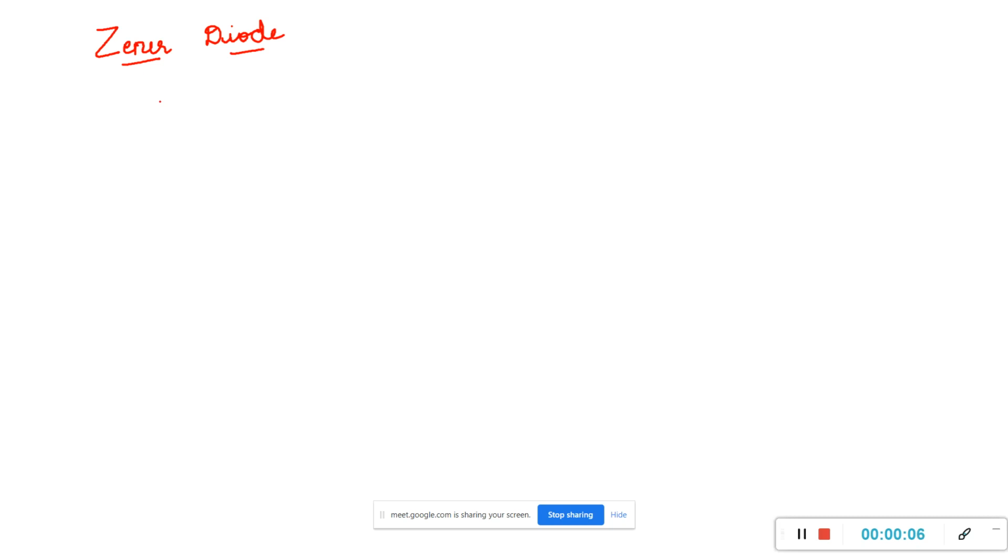So basically, Zener diode is a silicon PN junction semiconductor device which generally operates in reverse breakdown region. The Zener diode is fabricated with precise breakdown voltages by controlling the doping level impurity added into it during the manufacturing process. The Zener diode has a breakdown voltage range from 3 volts to 200 volts. In 1934, a physicist Carl Zener investigated this breakdown phenomena in the PN junction diode and hence the name Zener diode. Right? So, Zener diode is nothing but a semiconductor diode.